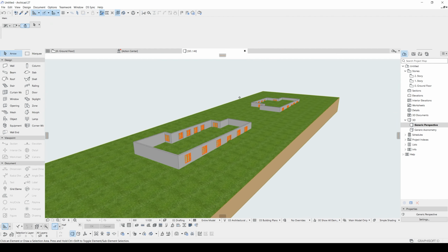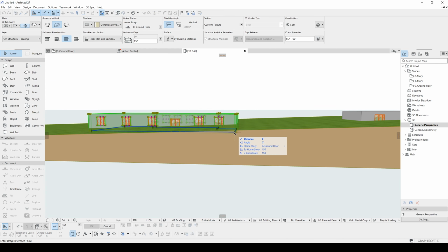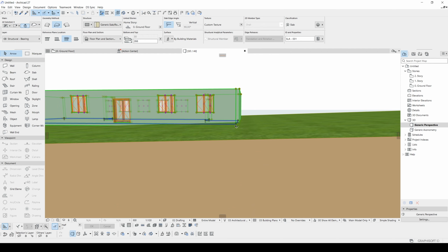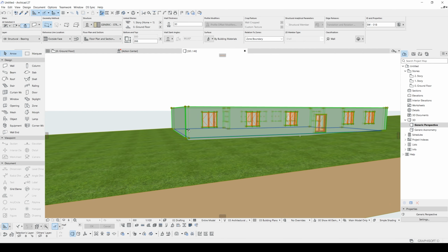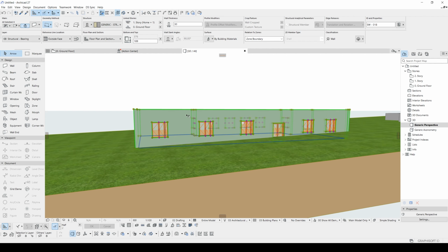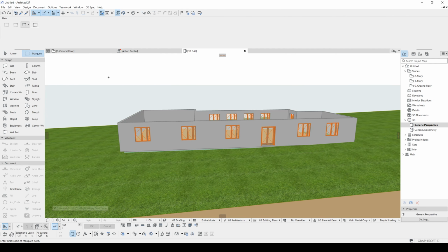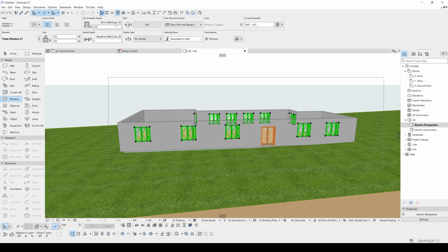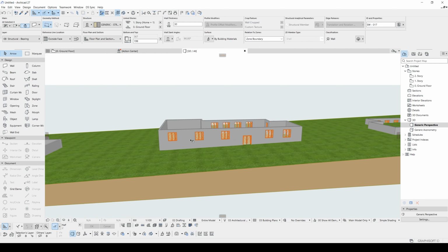We did the second corner and I want to fix more, and maybe we can fix the wall like this, but this time these windows don't work correctly. For this reason I will change the fill to story 0 and now I can fix the wall height from here.